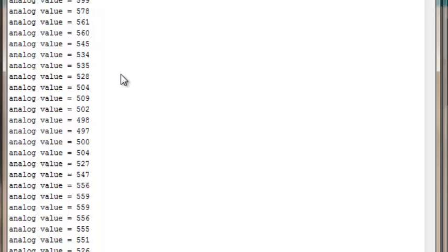As long as you can get close to that, what you could do at this point is hook a multimeter up to that center pole, and you'd be reading around 2.5 volts, because that's the midpoint from 0 to 5 volts. And whenever your analog to digital converter in your Arduino is pushing out numbers like this, it's right in the middle, in between that 0 to 1023. Well, this is just by way of review. Most people will be familiar with this. Now, the question is, how can I do something cool with that?